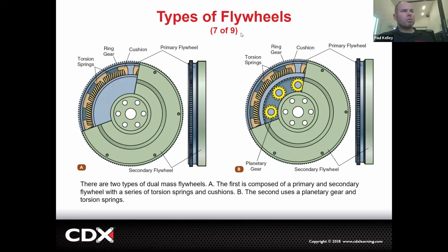And sometimes they even use almost like planetary looking little pinion gears and stuff in there. And that'll make it so your friction surface can actually bounce up against these springs, turn these little gears a little bit, right? Bounce, bounce, bounce. But your center part is bolted solidly to the crankshaft. Right. So there's moving parts in this. That's why you can't really machine this, because the whole thing bounces all over.